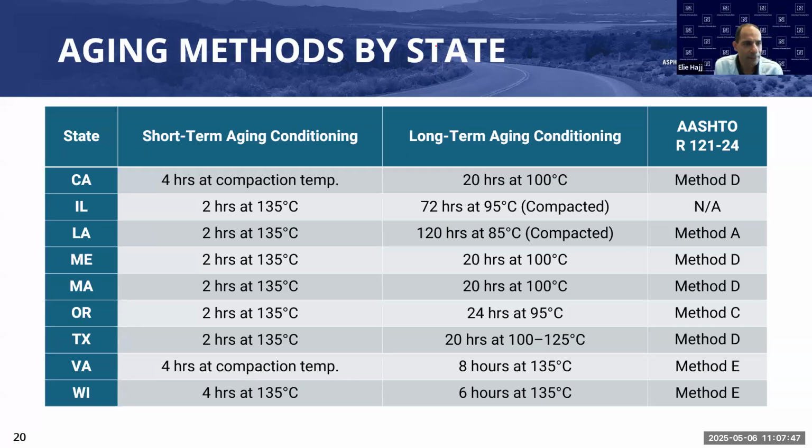Right. And if I may add, Derek. Absolutely, please. It all started with the NCHRP studies, which was mainly based on the binder stiffness. But what I've seen is that you use that number as a starting point, and then you look at your CT values and how it evolves with the aging, and then you may adjust that relationship between, for example, the 95C and 135C based on the BMD test, or maybe based on a mixture stiffness.